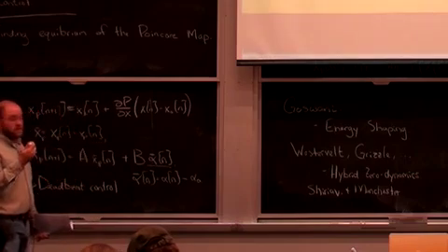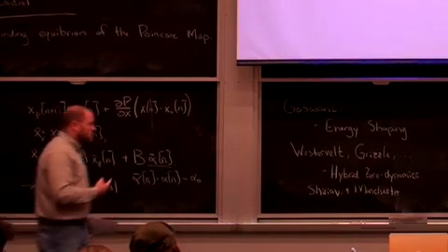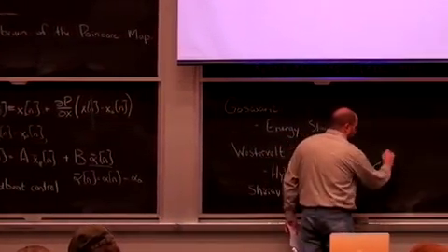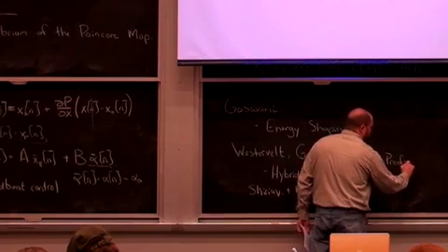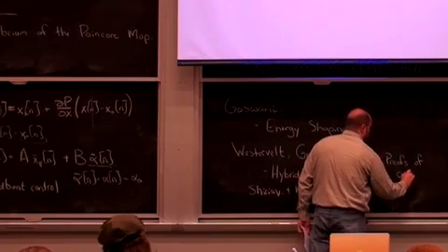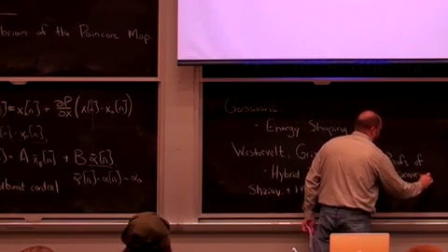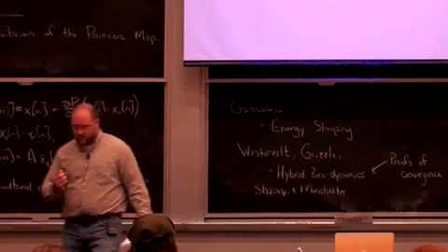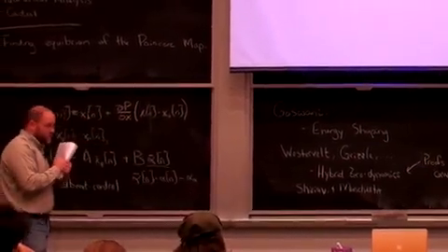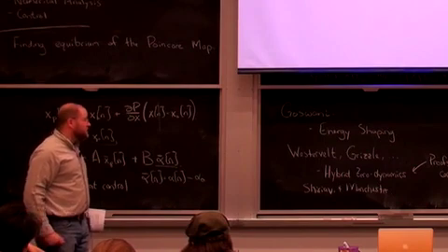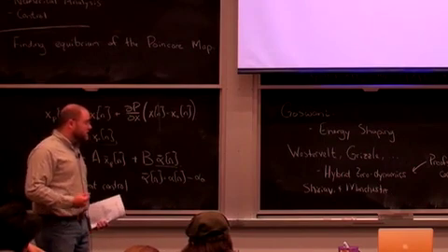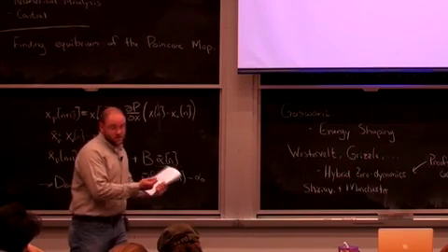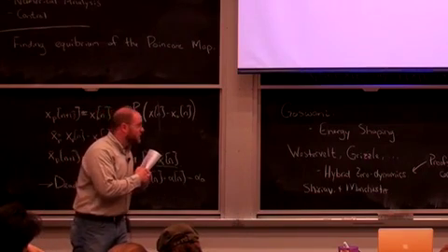It's sort of similar to the PFL idea. But these hybrid zero dynamics methods are one of the places where we actually have proofs of convergence. And the way they do it, like in partial feedback linearization, is that they find some desired trajectory of the robot, which has a periodic gait that they like.